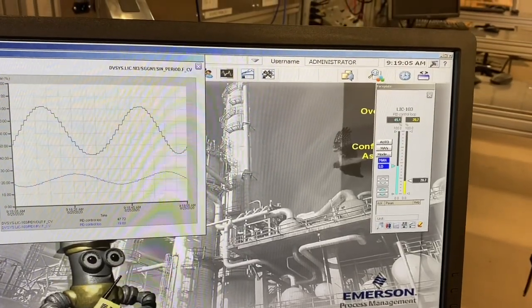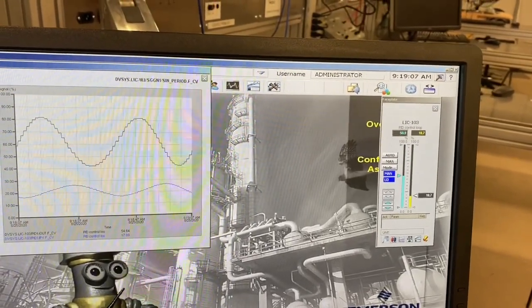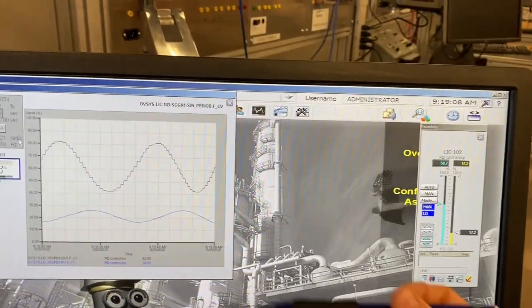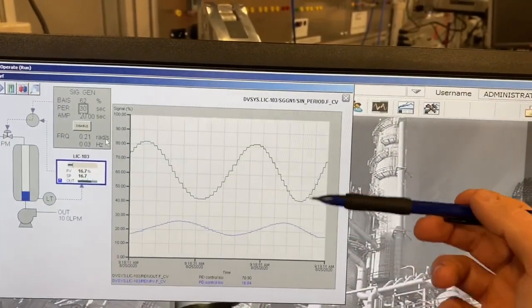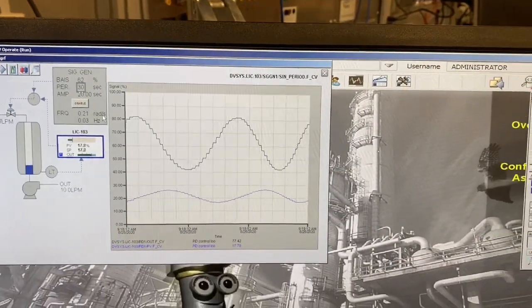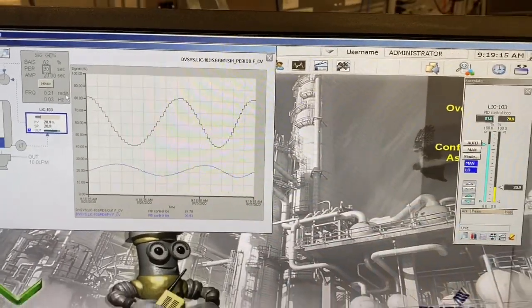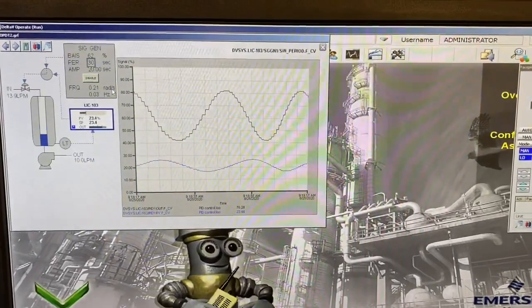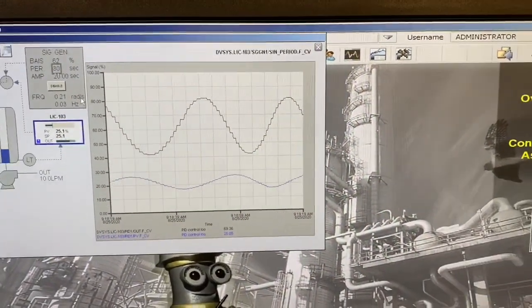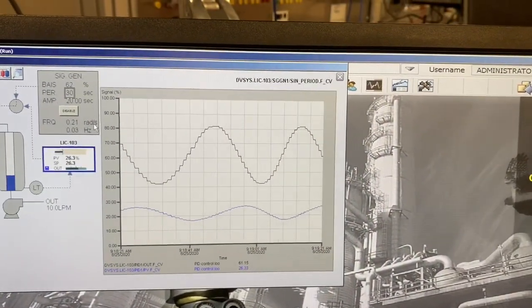So we're going to take those values, take the difference between those two. That'll tell us our peak to peak here, and we can divide that by 40 again to get our gain at that new frequency. So we'll do one more frequency here, and I think that'll give us a good idea and kind of prove that the integral process does what we expected.